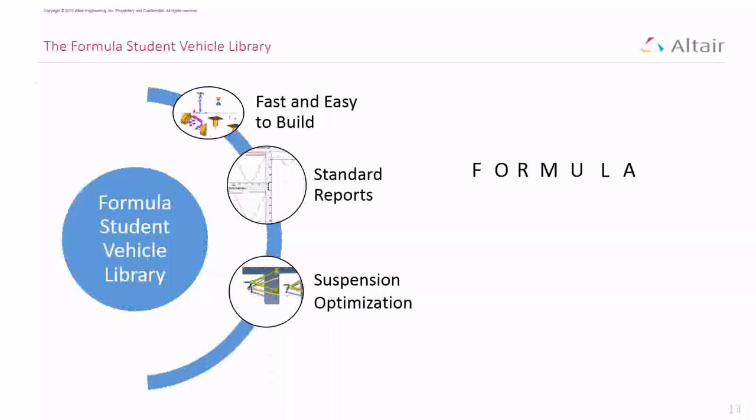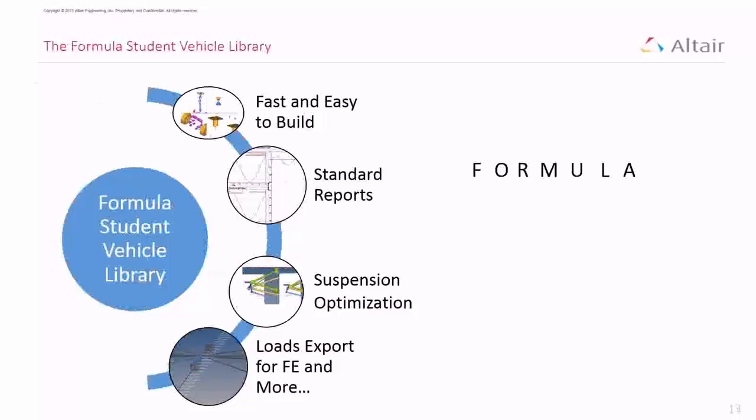And using the advantage of HyperStudy, as I had told you earlier, you can also optimize the suspension geometry of your front suspension or anything for that matter. And then you can export loads by requesting forces on one of the components, and these loads can be exported in FE format for further FEA analysis. So that is the formula we are talking about.